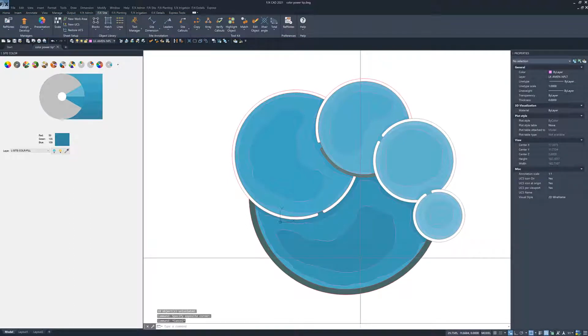It is important to set up these color hatches carefully. If one hatch has multiple areas, then changing the color for one hatch will change it for all of them. For example, in the edges of our fountain, we want to split them up so we can give them different color values. By splitting the edges up into more than one hatch, we have the ability to color them separately and add a sense of depth.